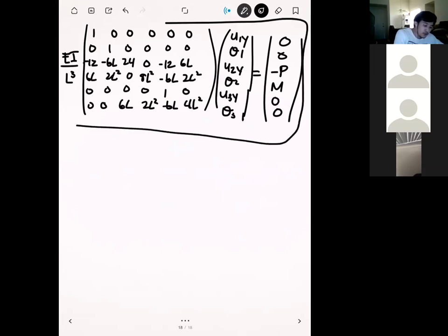That's our final global system, and that's basically as far as we can take this problem. Normally, if you had numbers for these, you could plug them in and solve in MATLAB. You can see the basic process of our finite element problems is still the same. For beams, we just have an extra degree of freedom and slightly bigger systems, but the fundamentals and the process we went over are the same. Are there any final questions on this?